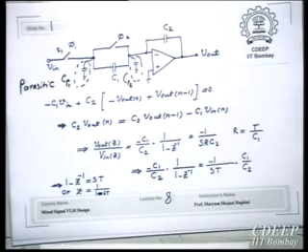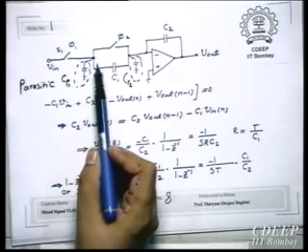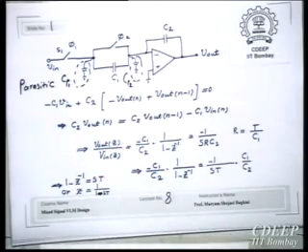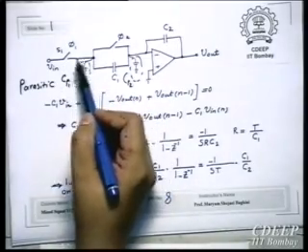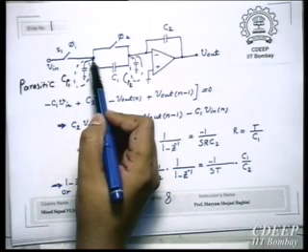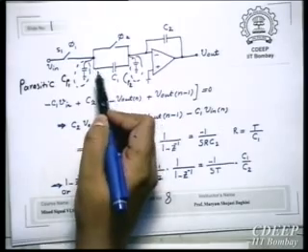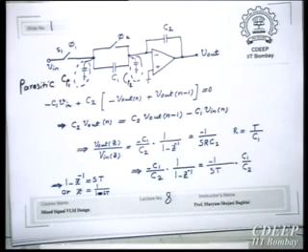Because parasitic capacitance will be a problem if it contributes to the amount of charge which is transferred to the output capacitance. But Vn changing, see, anyway, if we give it enough time, Vn is here. Therefore, the amount of charge which is stored on C1 still will be C1 Vn. There is no other charge.